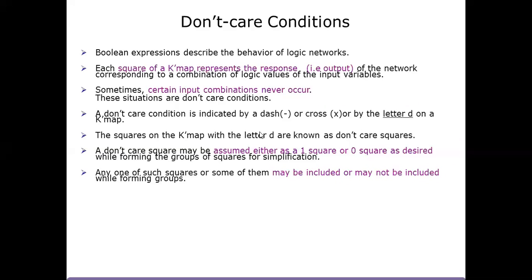We don't care whatever the value is there, because it does not occur in that particular hardware device. We can represent those don't care conditions by a dash, a cross, or the letter D. They are known as don't care conditions: dash, X or letter D.